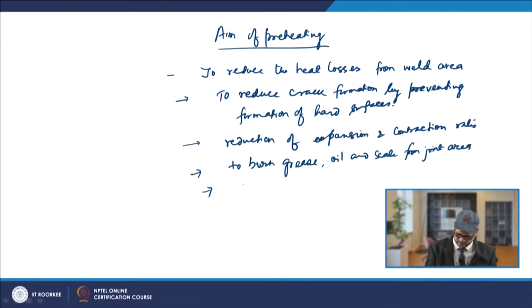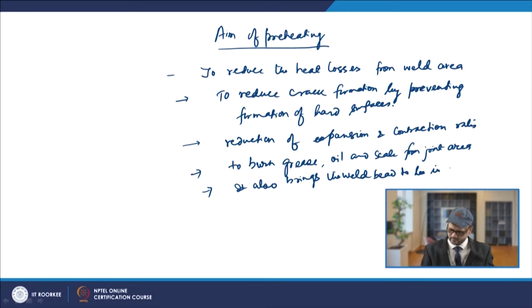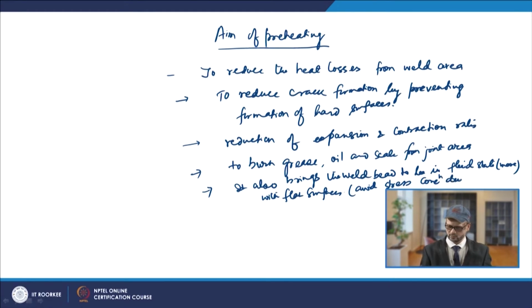So, preheating also brings the weld bead to be in a more fluid state, with flat surfaces, and that will avoid stress concentration due to the notch effect.